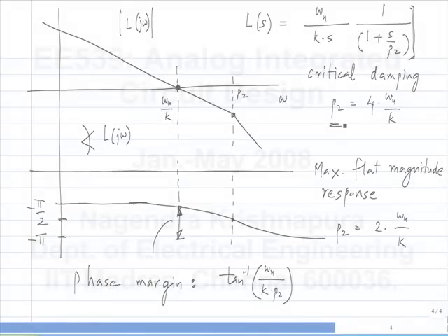Okay. So because when you are simulating it, you may not know exactly where the poles are. You can do pole zero analysis, and that can give you some problems as well. So you try to do it by evaluating the steady state response. In that case, the same criterion can be stated in terms of phase margin. Okay. So for this, what is the phase margin?